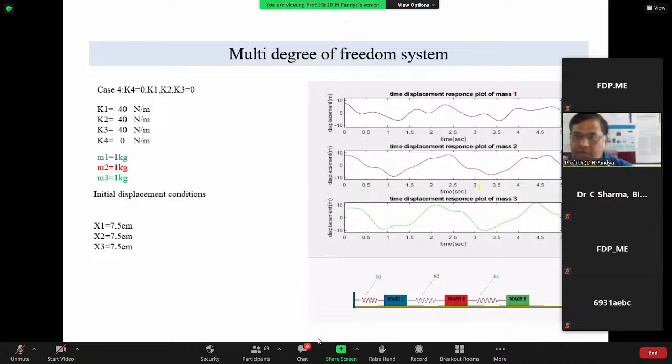In our conventional lathe, we have a speed range from one speed to another, but some speed range is missing. It is intentionally missing because that speed range is not good for the machine tool. It causes a large amount of tool vibration.